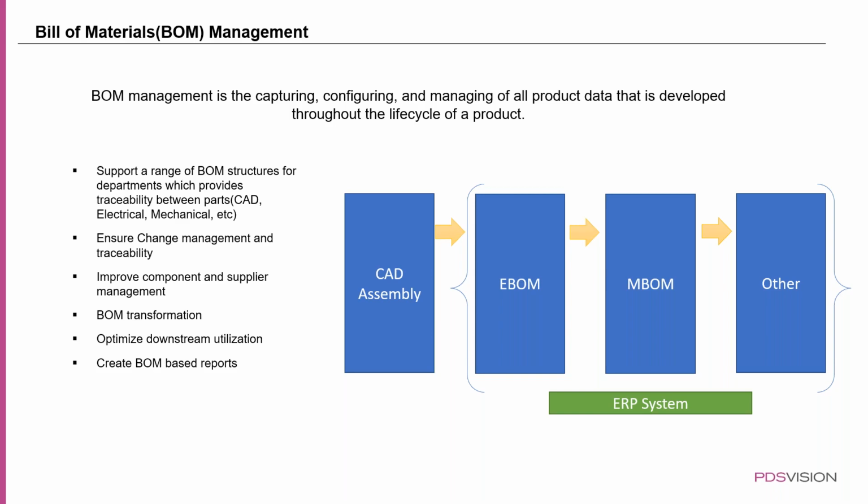So you can also have different reports exported for CAD assembly or engineering bill of material or M bill of material. They could be in Excel sheet format. We can also export them to an importable spreadsheet. That means you can export it to an Excel. You can update that particular Excel, say you want to make changes to some of the components, its quantities and all.